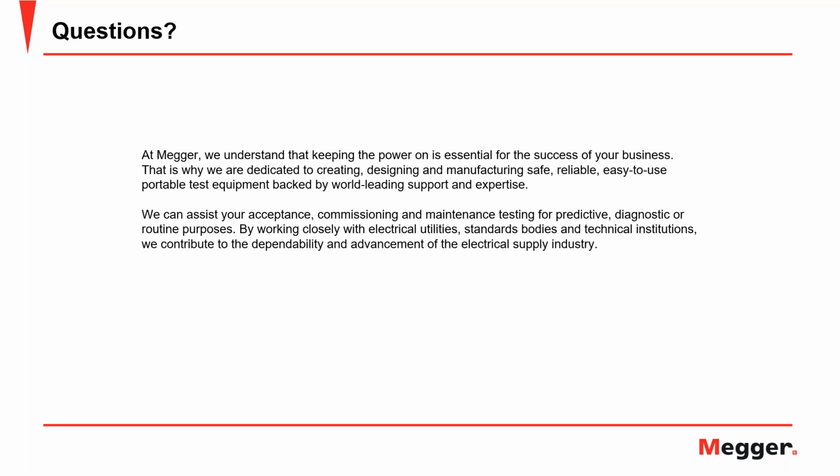For all practical purposes, the impedance of the cable is much greater than the resistance of the breaker itself. So if you have longer length, then you are increasing the impedance of the circuit. And as you know, current is a function of voltage and impedance.